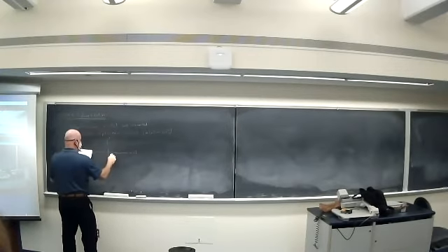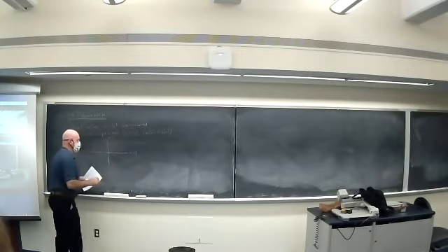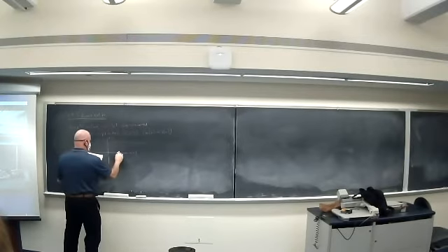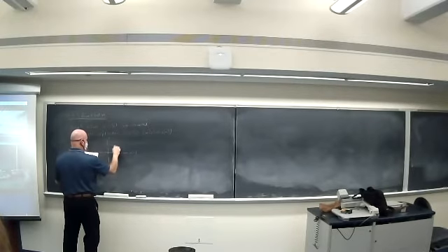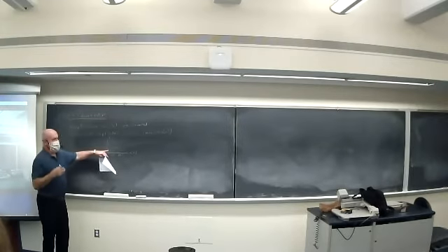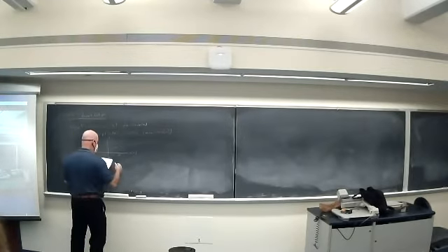So we typically have values between minus 0.5 and 0.5 converted to 0. Okay. And values between 0.5, trying to get the same distance, and 1.5 are converted to 1. Okay. And we only have a fixed set of allowable values in V of n.